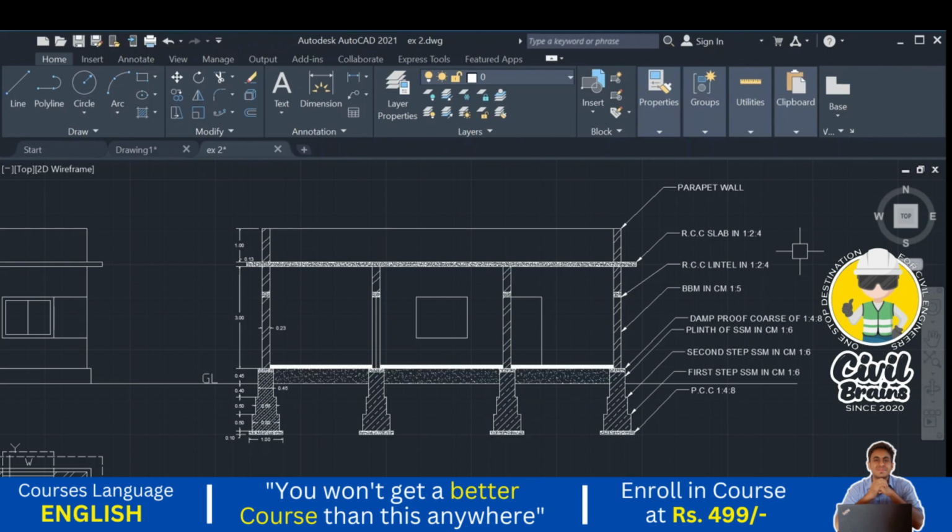After that the superstructure, lintel, slab, and the parapets, and all the sections. Once we cut the building in this cross section, whatever things will be shown, that is doors, windows, everything we have shown here, correct? We have shown the sand filling also. We have shown the flooring bed also, and we have shown the hatching to all the elements of the structure, and we have shown the dimensions for all the structures. And after that we give the specifications also.